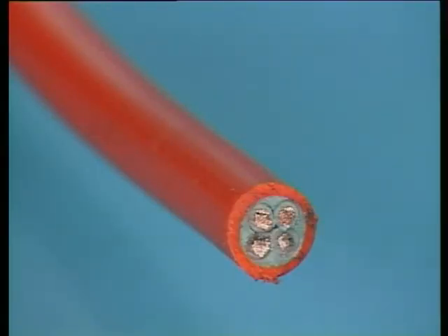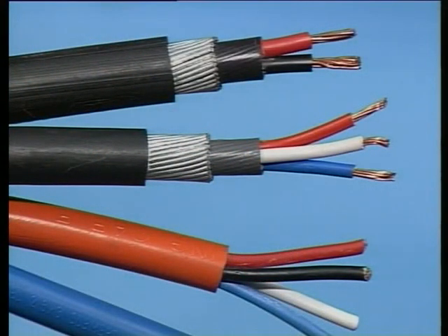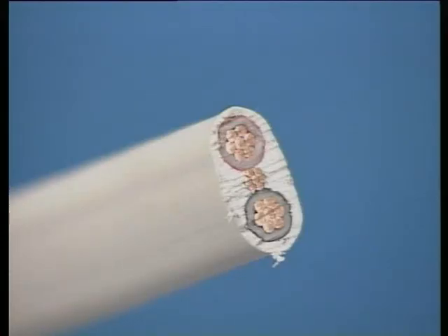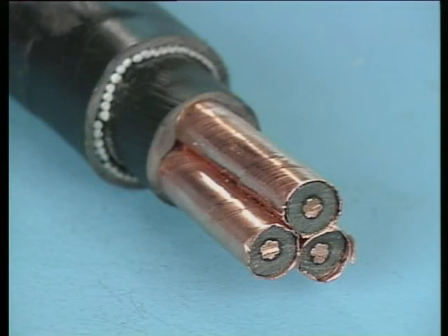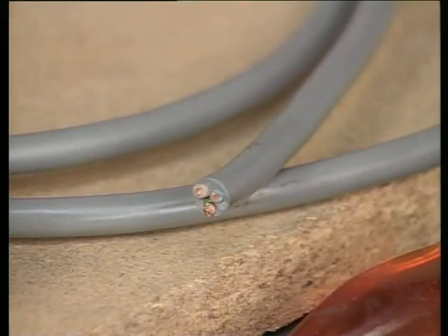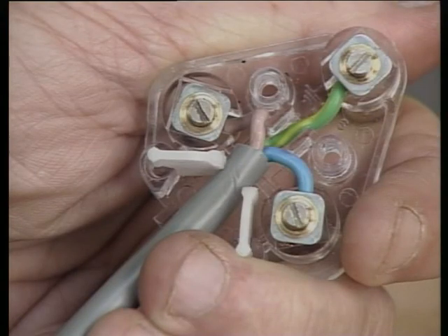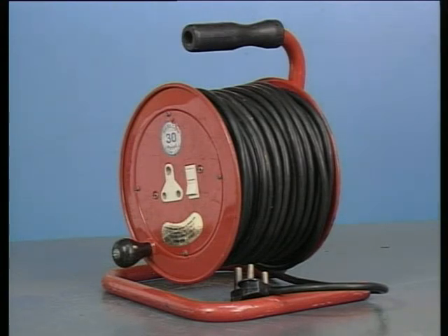Multi-core cables are those in which 2 or more conductor cores are encased together in one unit. The construction of multi-core cables may be as simple as this so-called flat twin and earth, used mainly in low-cost domestic applications, or as complex in construction as this XLPE medium voltage cable. A very commonly encountered cable is the so-called cab tire type, used extensively for portable power supplies or extension leads at home and in industry.